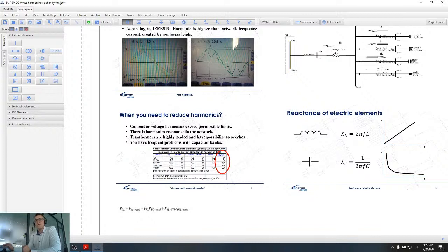So then we have a question by Mr. Thomas, and the question is, does high frequency harmonic current cause increase in temperature of the conductors? So of course it causes the increase in temperature, first of all because of those eddy current losses, as I have mentioned. So these are circulating currents which appear in the conductor, and this of course causes temperature increase.